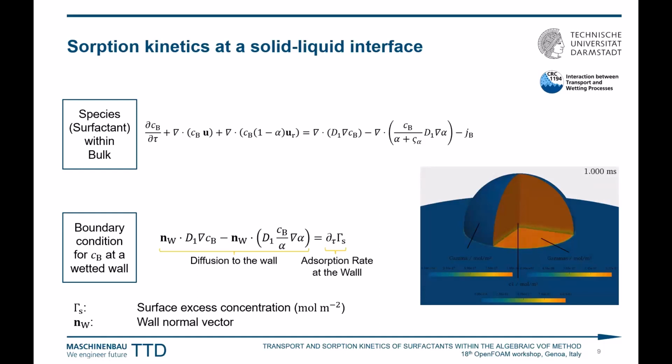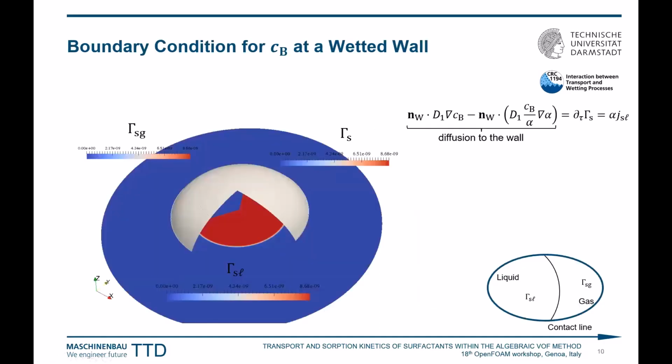But here you can see an issue straight away: this works only when the drop is stationary. When the drop moves, there might be surfactant which is not previously on the liquid surface, meaning there might be surfactant away from the drop, and once it moves, somehow you have to take care of that also. That is where you have to implement more data into this boundary condition. That is what is mentioned here.